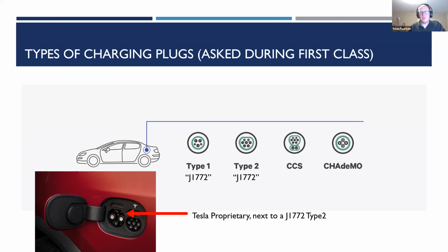Right. So the fast charge. There's what they would call AC charging, which uses the onboard charger in your car to convert the alternating current from standard wall power into direct current for the battery. And then there's fast charging, which has an off-board charger that's much, much larger.